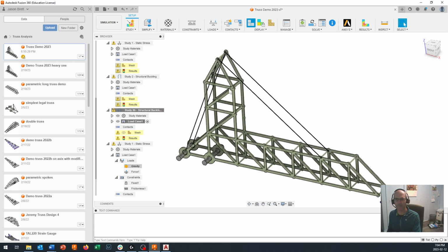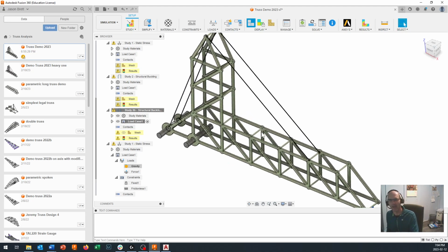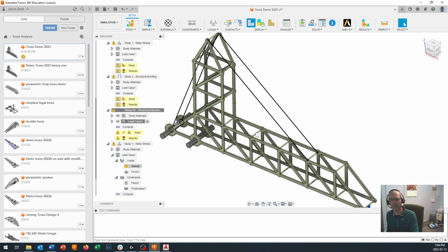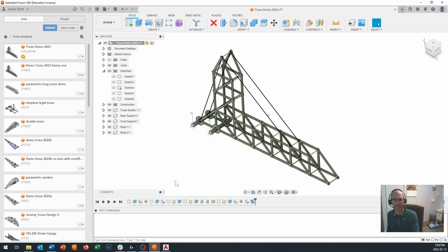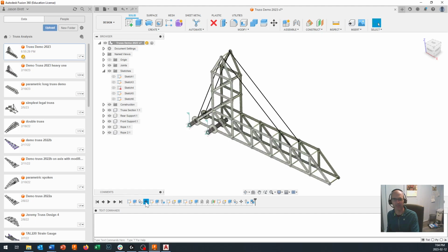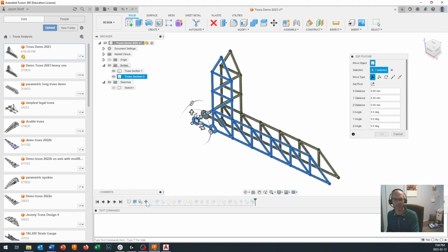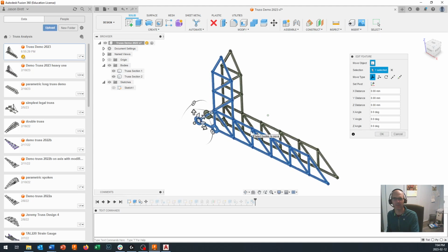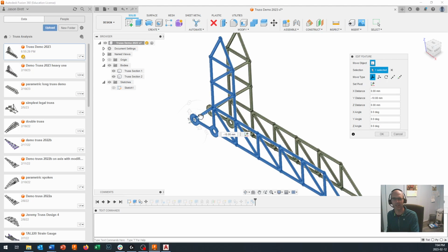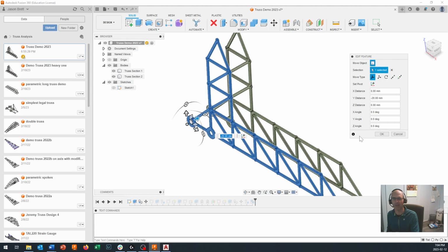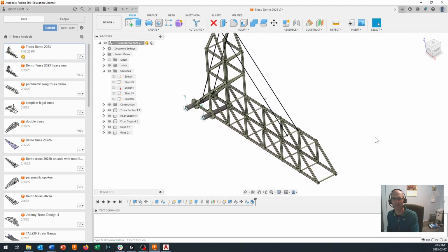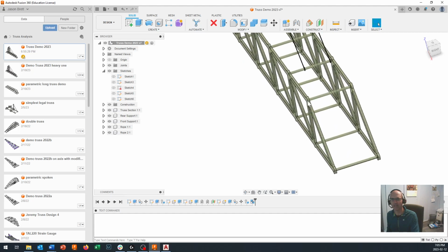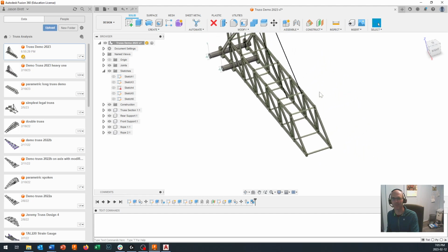This is really useful if you want to do a few different things. So for instance, I made this 40 millimeters apart in the middle right here. I'm going to go back to my design, okay? And where I did that copy right in here, there's that move command. If I double click on that, I moved that 43 millimeters already. I can come in here, I can move that another 20 millimeters out, and now I've got it sitting 60 millimeters apart.